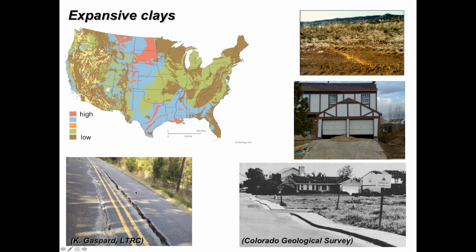This one in the lower left here is a photo from Louisiana. You can see this very large crack occurring in this longitudinal fashion along a roadway here. This is fairly common, a common looking distress pattern for a pavement system founded on expansive clays, and it develops for a very specific reason.